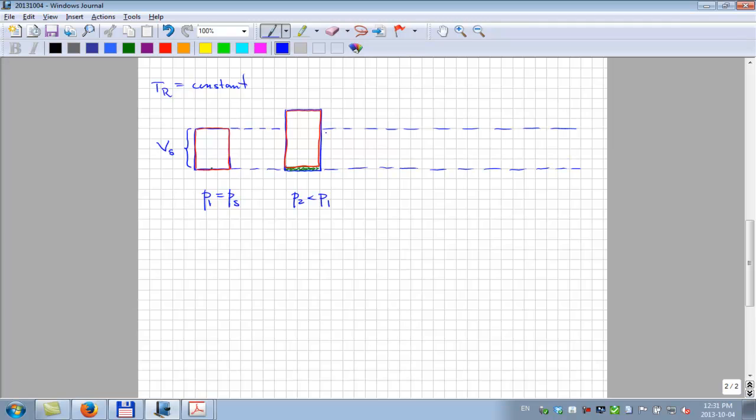So at this point, we've got a total volume that's bigger than the initial volume. And here the experimental procedure is going to be such that we try to mimic what goes on in the reservoir by always maintaining a constant hydrocarbon pore volume. That's kind of the concept. And to return this new cell volume back to the original saturated cell volume, we can take away all of the oil, part of the gas, or we can take away all of the gas. Those are the two options.